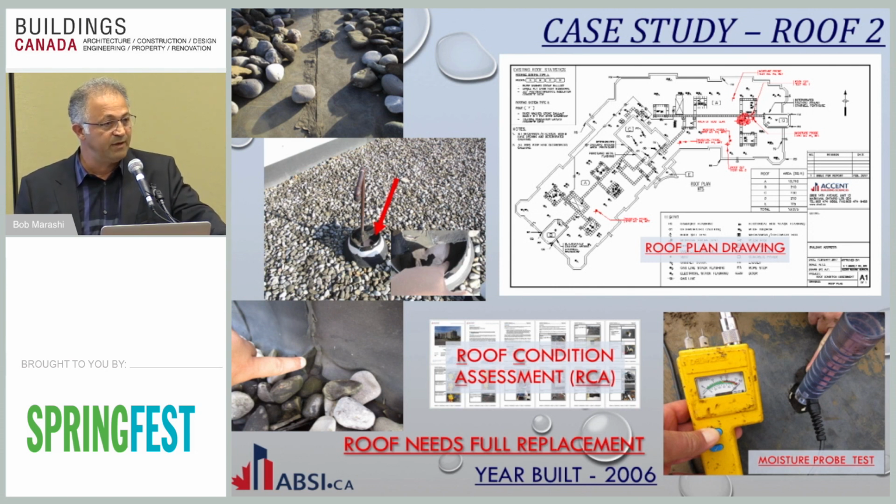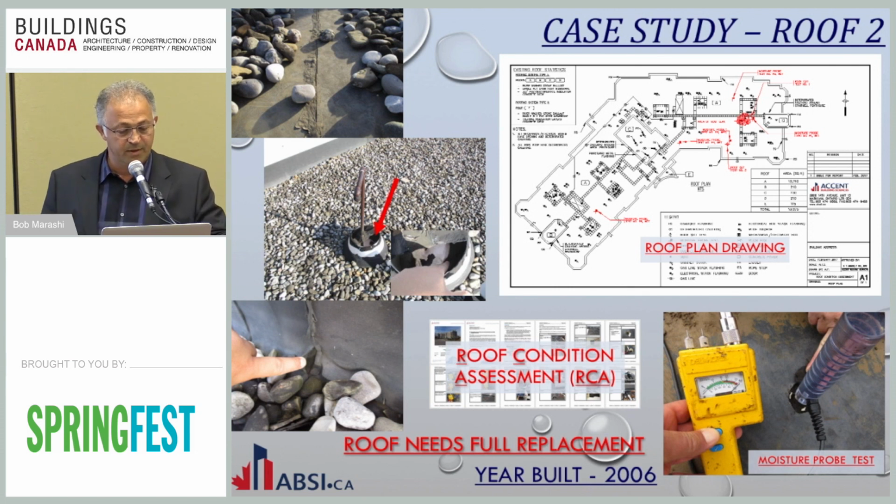It's in the hands of the condo board of the building to decide what they want to do with it. It has to be replaced because if you don't replace it, there's wetness, there's concrete, it's going to get damaged. There's no vapor barrier there. The original contractor who installed the roof did not put the vapor barrier on.